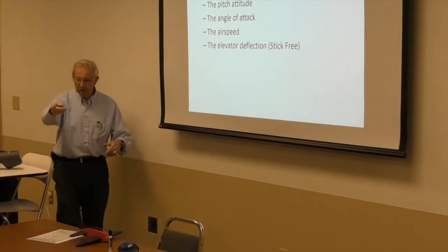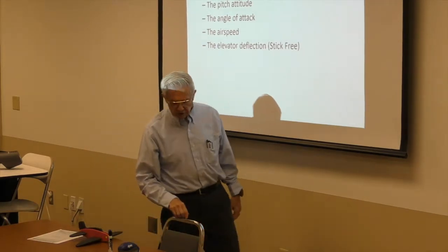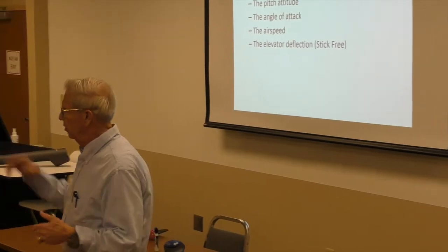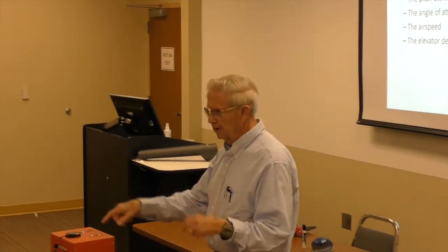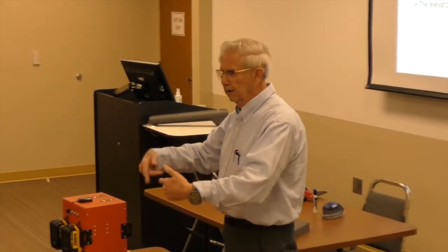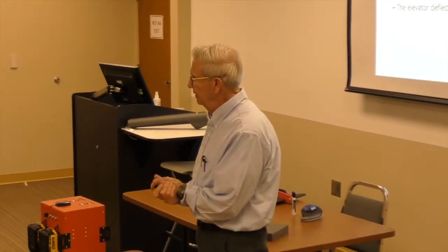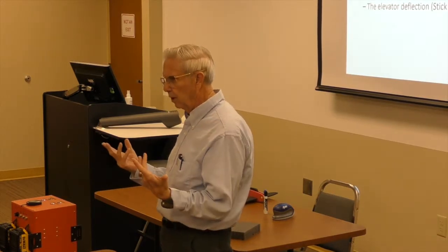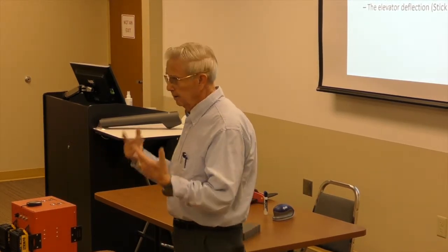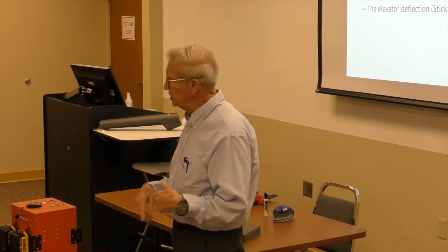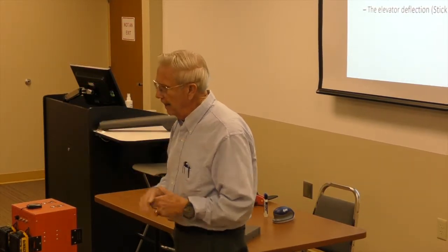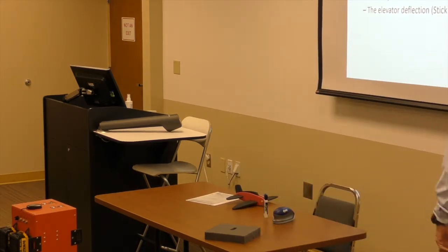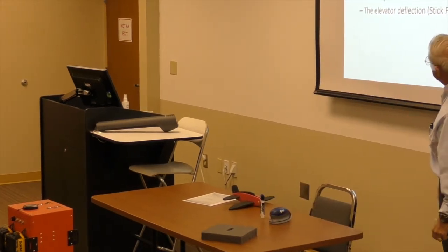Okay, so when we do longitudinal stability, we'll try to combine that when we do static. We'll do, say, the climb case static, and then we'll turn this thing on and let it run, and we'll record the dynamics for climb. And then we'll turn around and do the statics for power approach. And when we get through with the statics, we'll turn this on and record the dynamics in power approach, okay? And so these will be important parameters.